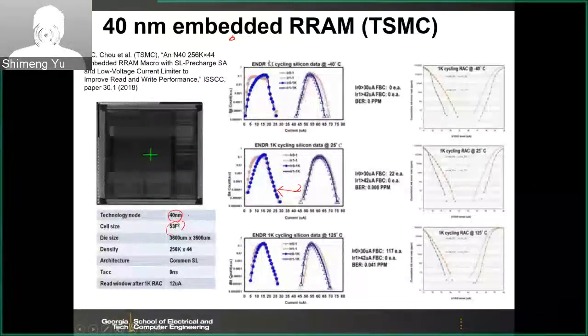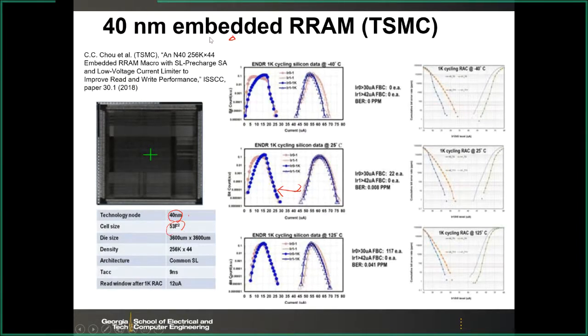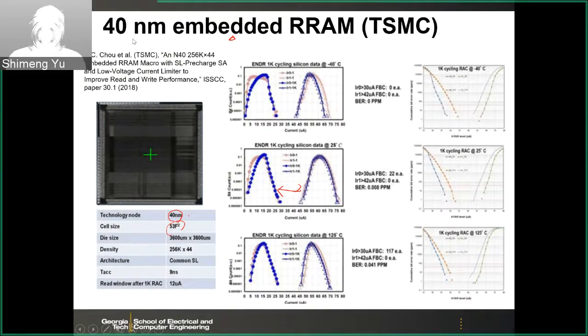And just one more note, TSMC actually commercialized this technology. You can do the tape out with TSMC basically with the 40 nanometer process. They offer it as one of the solutions for embedded non-volatile memory at the 40 nanometer node today. Customers are using TSMC's process to design 40 nanometer RRAM today. My research group also has been granted access to this particular technology, and from our group we have designed a few generations of this 40 nanometer RRAM process.